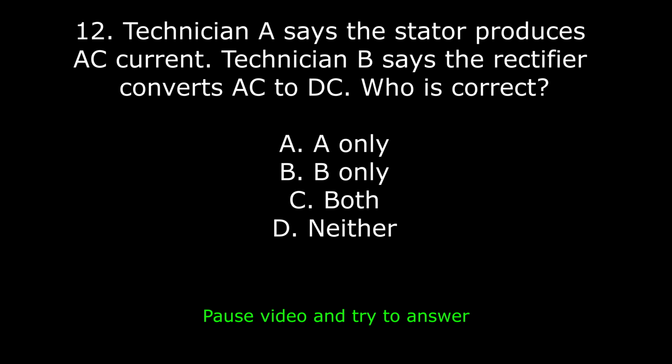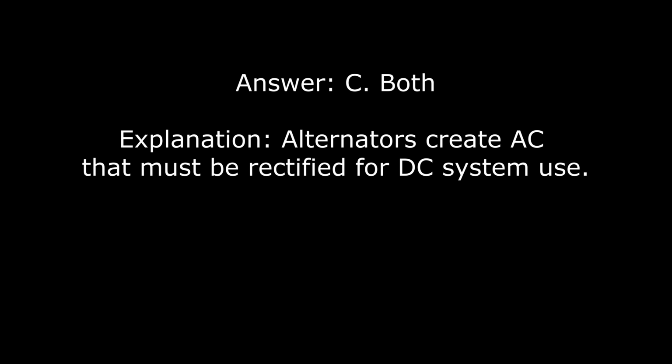12. Technician A says the stator produces AC current. Technician B says the rectifier converts AC to DC. Who is correct? A. A only. B. B only. C. Both. D. Neither. Answer: C. Both. Explanation: alternators create AC that must be rectified for DC system use.